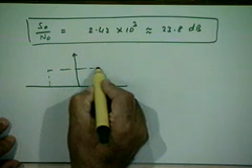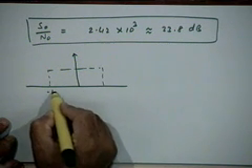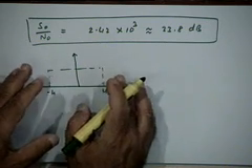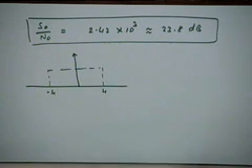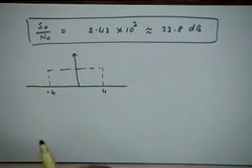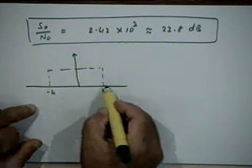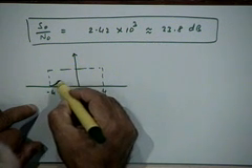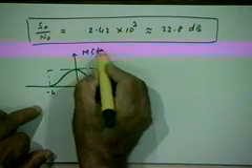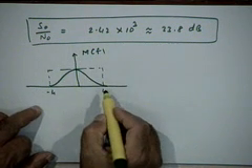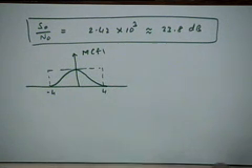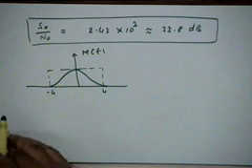By saying that the signal has this kind of a spectrum, basically what we are saying is we can use the final low pass filter after demodulation to be a filter of this kind of shape. Suppose I were to tell you that the power spectral density within this bandwidth is distributed like that. The message spectrum is not like this but like this. Then using an ideal low pass filter as a final baseband filter is not the best thing one can do.